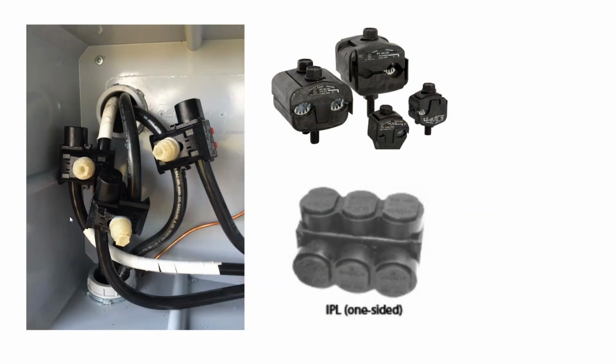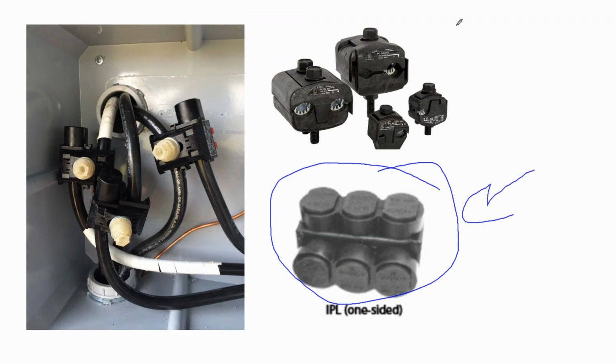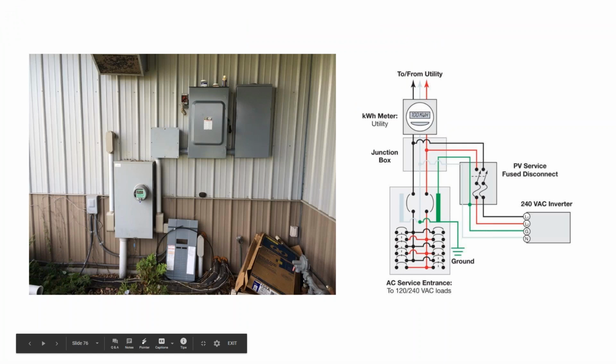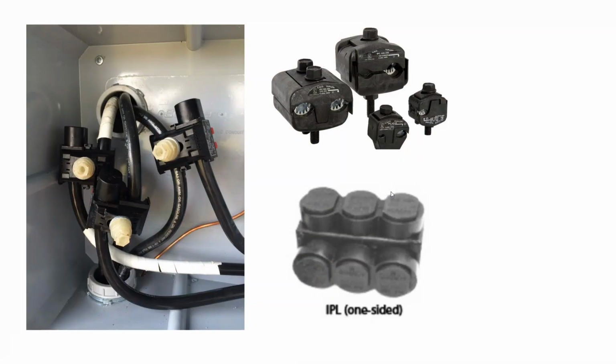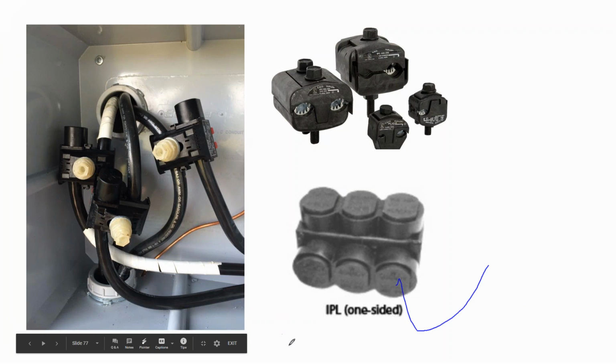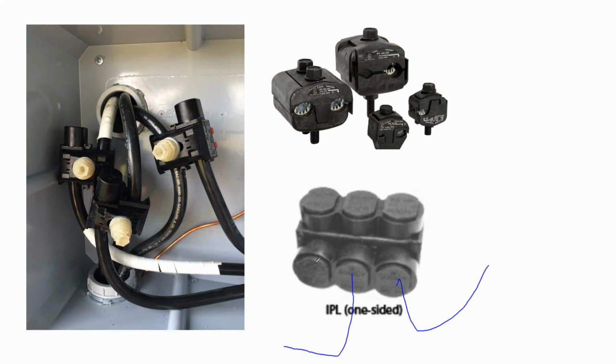You know, what I'm picturing here is this is where the actual cables get interconnected to the grid. This is called a tap connector. These are piercing insulated tap connectors. These are standard tap connectors. But basically, this piece does this thing here. It makes the connection point. So you've got wires from the grid coming in one side, wires from the solar array coming in the other side, and wires going out to the electric service panel. They're all tapped together at this point.